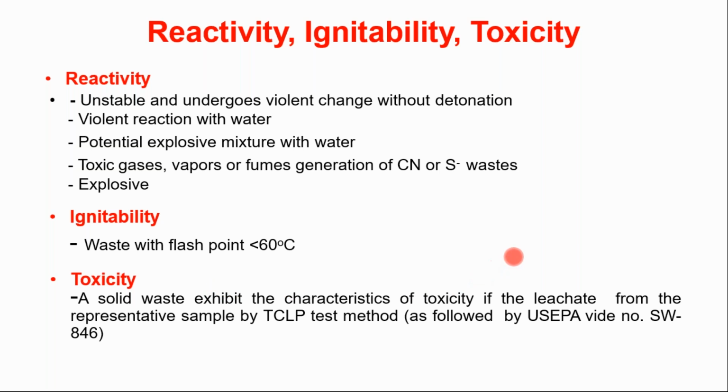We have to measure the LC50 value, LD50 values, TLVs, etc. for getting these types of outcomes. That is nothing but the lethal concentration, lethal dose, or threshold limit values. Depending on the characteristics and the physical state of the substance, we can observe these types of outcomes.